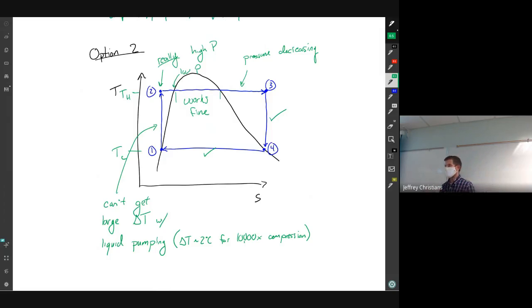So both of those systems, we would have to have a turbine integrated into a heat exchanger that could both extract work, lower the pressure, and keep temperature the same. And it would just functionally be really hard to design, right? It's easier to design a turbine that we just strap some insulation around, keep it close to adiabatic, than it is to have a turbine where we have, I don't know what you would have to do even.